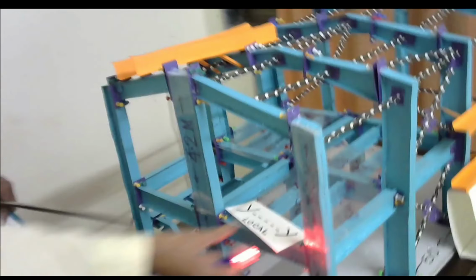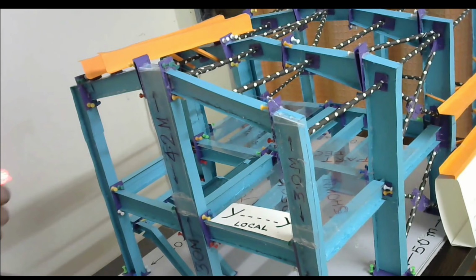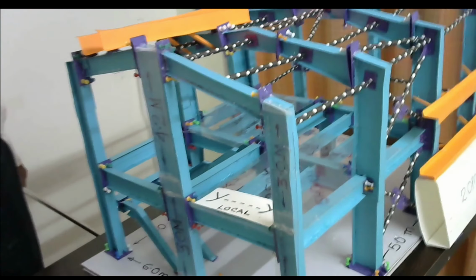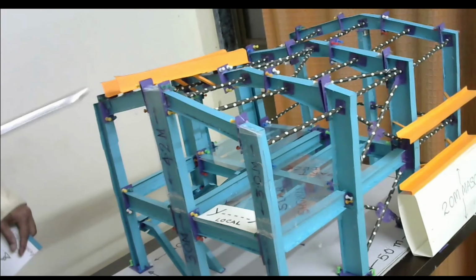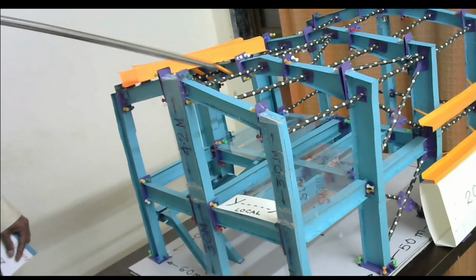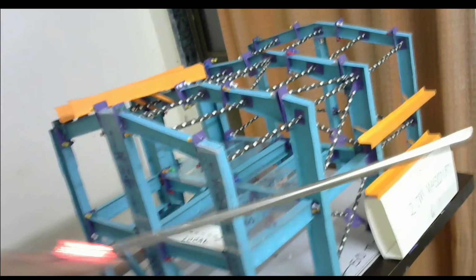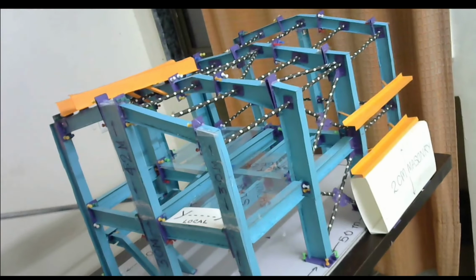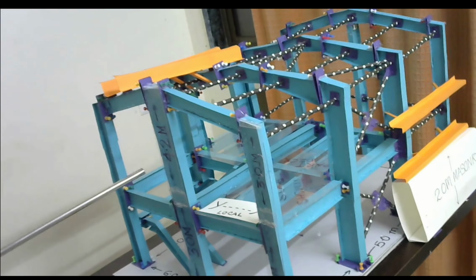So for this column, about local YY, the top part is hinged, but it is resistant against translation. The translation is being prevented through the roof braces and the strut and the braces at both sides. The translation of this column is resisted through this strut, then through the braces at the roof, and then the forces go to the foundation, through the portal frame to the foundation. So it is a non-sway frame. So the LY parameter also remains 4.2 meter.